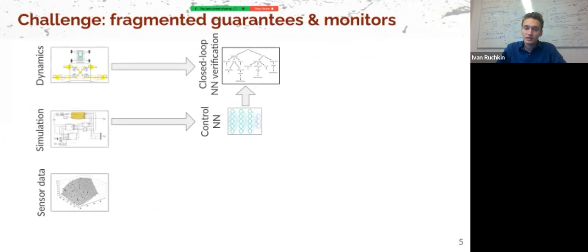Essentially, it's a reachability analysis that composes the dynamics in the controller and explores if it's possible to violate safety, which means failing to avoid obstacles or losing the sight of the pipe for the case of the underwater vehicle. If our controller is good, the safety verification will give us the verdict safe. That means it's impossible to violate safety properties using this controller. That's a great property that we want to have and a strong guarantee.